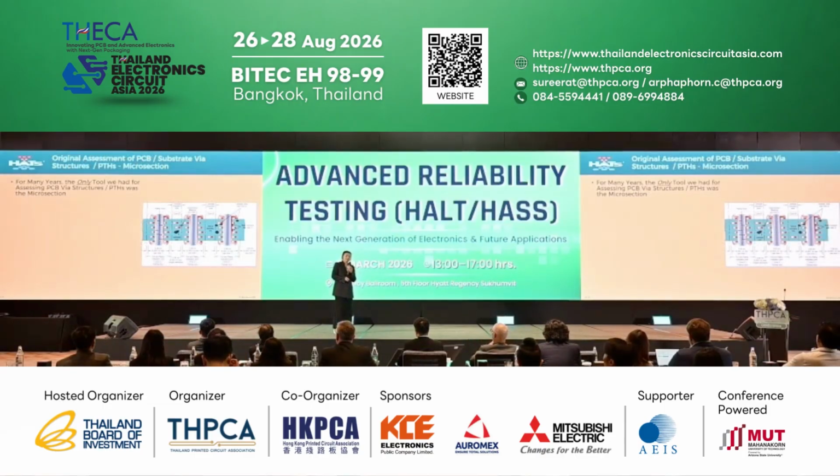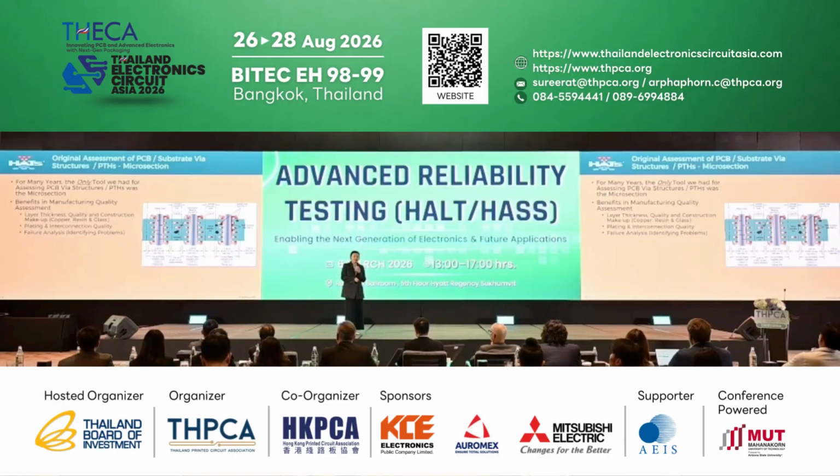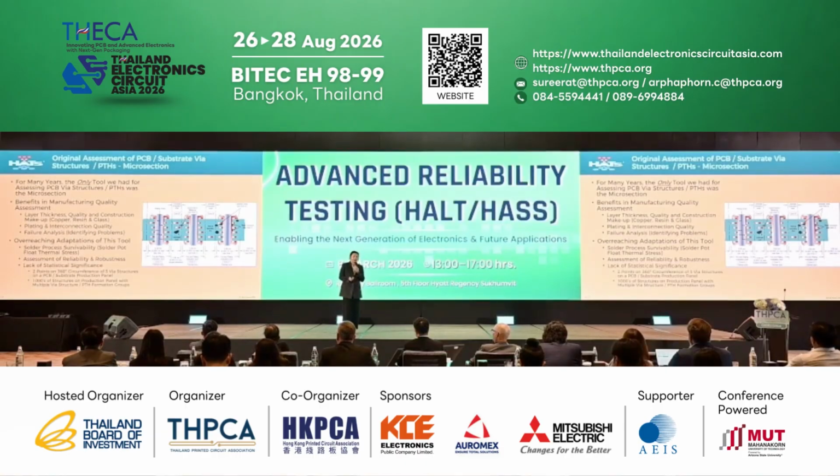For many years, microsection is the only tool we can use to evaluate PCB via structures and the PTH. The benefits in manufacturing quality assessment is with microsection, we can tell a lot of things. For example, when we look at the microsection report, we can look at the layer thickness, the quality, and the construction makeup. For example, copper, resin, and the glass structures.